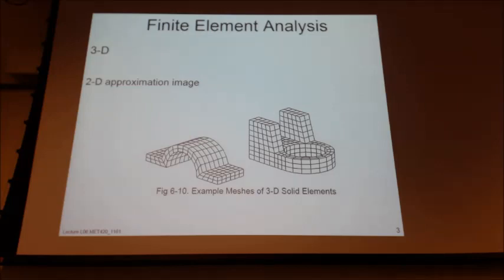Now, 3D is certainly a little more complicated, takes a little more effort, certainly takes more analytical power to calculate and determine. So to help us out and ensure that we're going in the right direction, that we have good values from our 3D model, it's always an excellent plan to do a 2D approximation of your 3D solution, if for no other reason than to give you the limits, the boundaries of what your 3D should land in between.